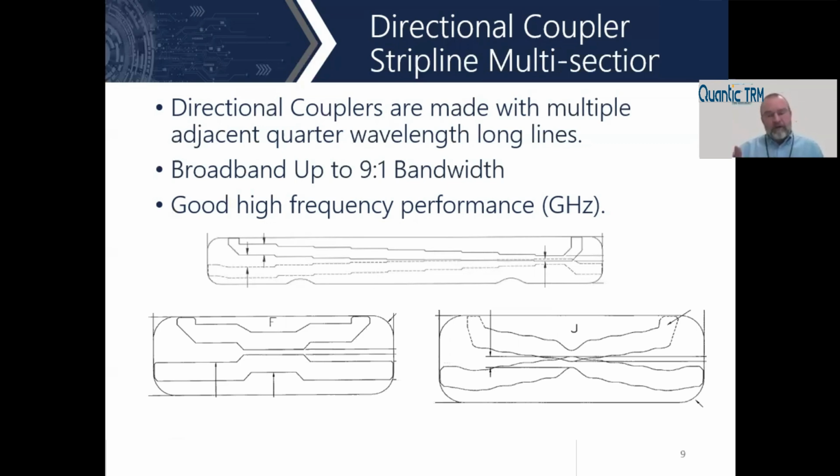The last discussion was talking about a single quarter wave section giving you an octave bandwidth. Very often we need more than an octave's worth of bandwidth. How do we do that? By superimposing multiple sections, we can mathematically build a power series that has a broader bandwidth than the single coupled section. Basically, if you go through some of the ideas of Chebyshev tapers and how they're realized by using a power series, you can add multiple quarter wavelength sections along with varying coupling values, and when you add them all together, you end up with an equal ripple function that can be over a very broad band.